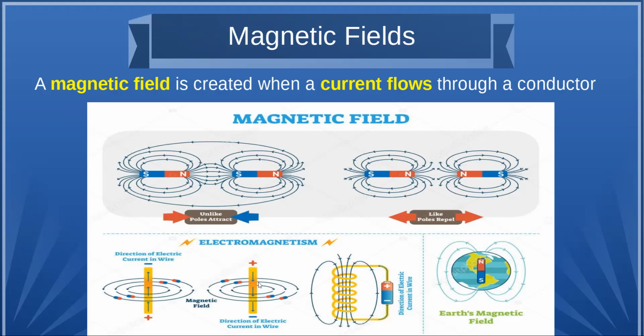Now, a wire by itself has some inductance, but basically you need many turns to get a lot of inductance. And to get even more, you put a material in the core that has what we call permeability, and it can concentrate the magnetic lines of force.